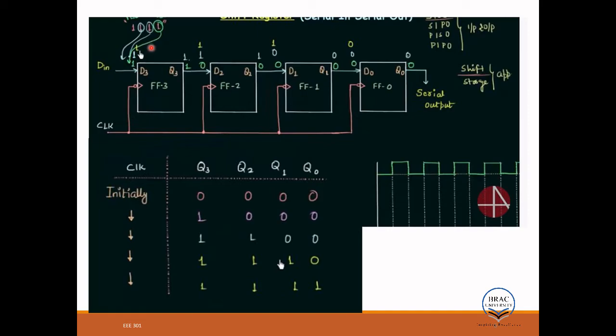So if you look at here, this one is for preset, right? And later on, when your override is low due to the clock, this will be transferred to the other flip-flop. So it's shifting the 1 into different flip-flops. That's why it's a typical application of a shift register, you can say. Okay, so it produces a ring kind of cycle, if you look at here, right?